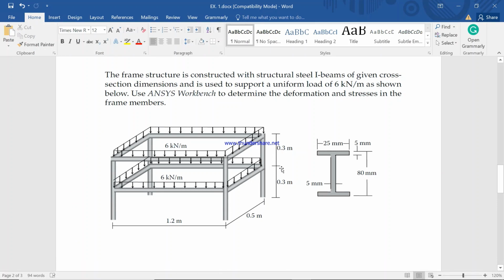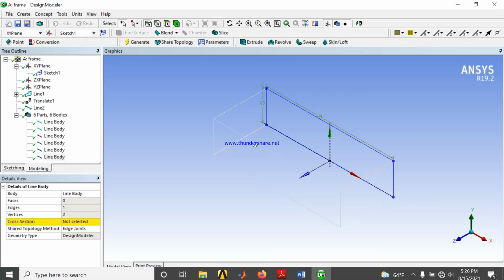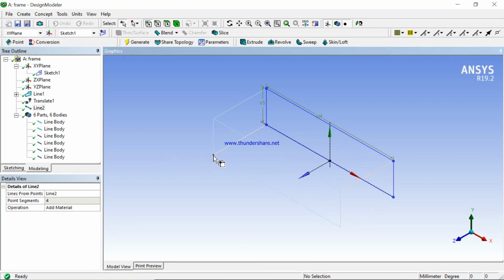So the lower vertical sections, they are 0.3 meters down. That is 300 millimeters. So we are going to put this by clicking at a point. Sometimes it is not locked in. Look at these filters. So we should select a filter for the point. Don't forget that. So when you select this point, I'm going to say, okay, let me select all the 4 points by pressing Control.